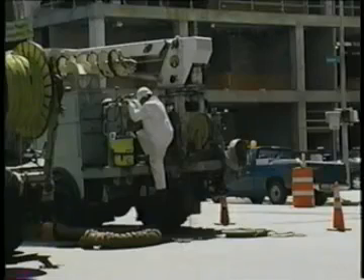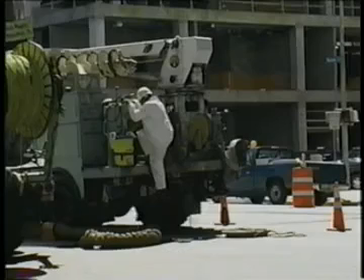Inform the local electric utility of work near overhead power lines 48 hours in advance if possible, so that arrangements can be made to de-energize, relocate, or insulate the lines if necessary, and to ensure that they lock out the automatic reclosure system of protective relays for the duration of the work.